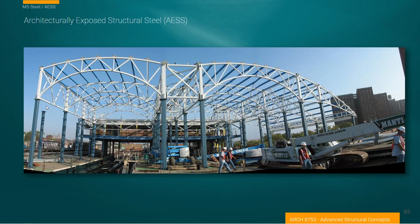And because we're willing to jump into that world of customizing our steel, we can have a lot of influence even on more mundane projects, like in the case of the bow truss here, the curvature of the top and bottom chord. One is done for drainage. Another one is designed maybe for clearance and/or appearance.